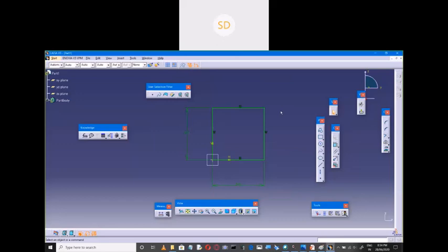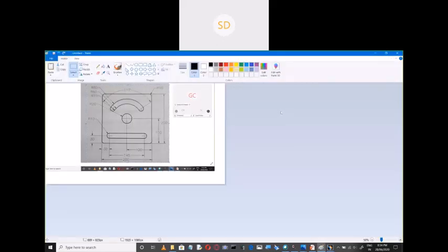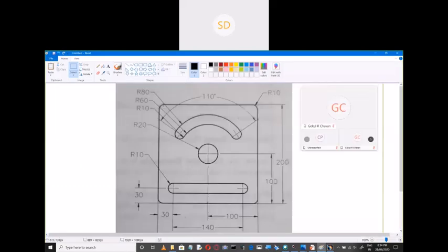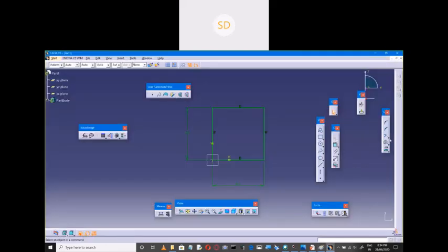Now you made an outer loop. You made an outer loop of the diagram. Let us look out. Every corner has a 10 mm radius. Okay. Let us go for the corner here. Okay. Click this portion. This portion. Okay. You provide radius 10. Then select.